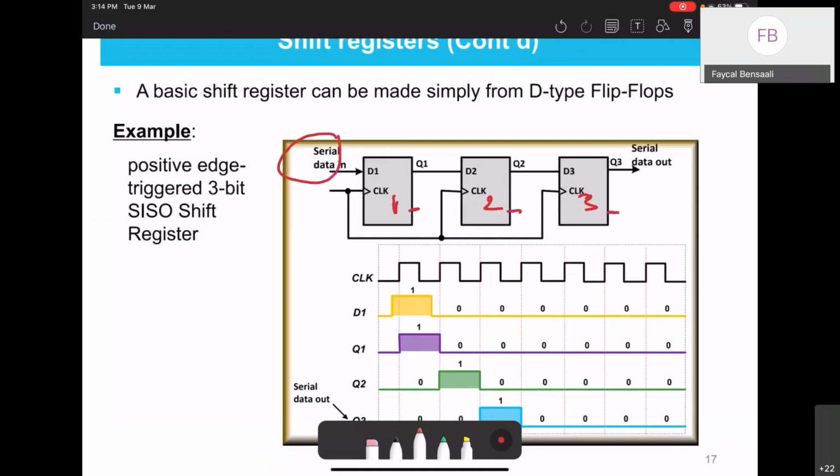And this is the serial in. So this is my circuit. As you can see, it's one circuit that has 3 flip-flops and 1 input. Of course, the clock is always there. In addition to the clock, we have the D as 1 input, which goes to the first flip-flop. And then internally, we connect the Qs to the other Ds, and the output is just the final Q.